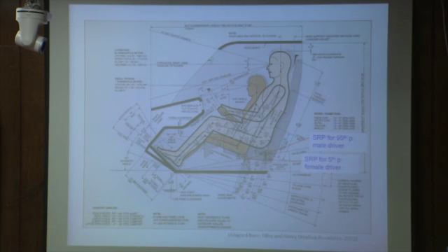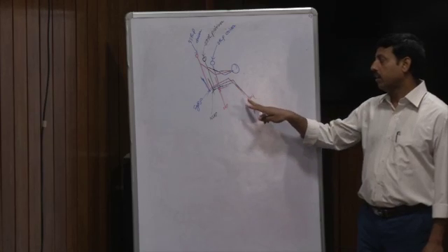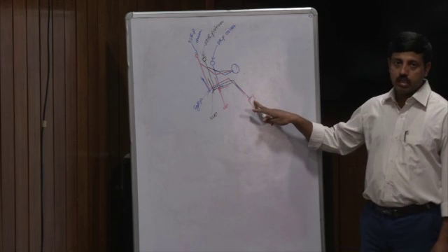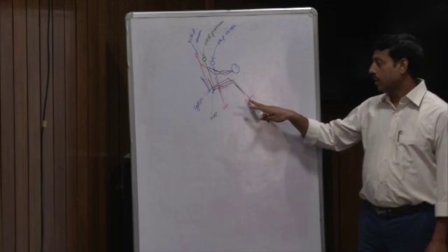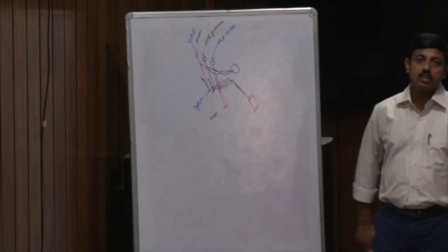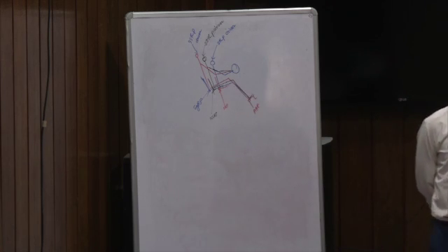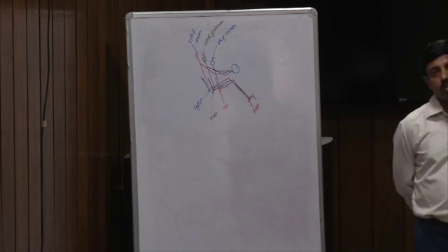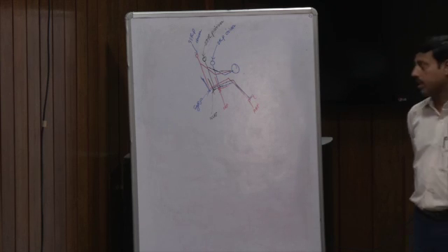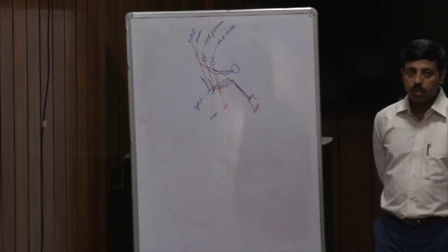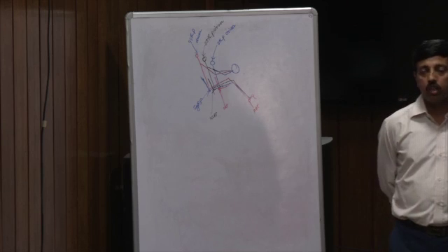So the accelerator heel point can be defined as a point on the vehicle floor, while drivers are keeping their feet on the accelerator, where the heel is touching. That contact point is known as the accelerator heel point. This accelerator heel point is also important for positioning the driver on the occupant seat.